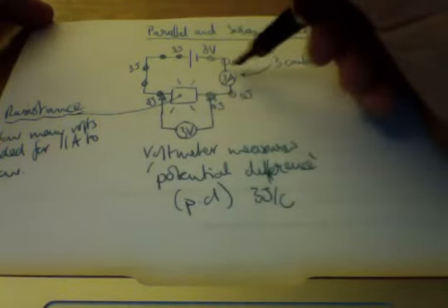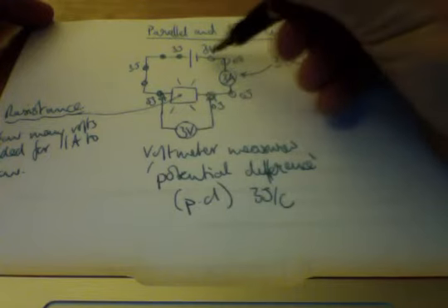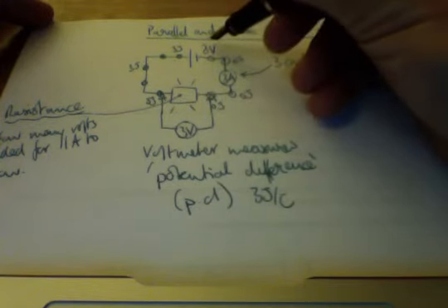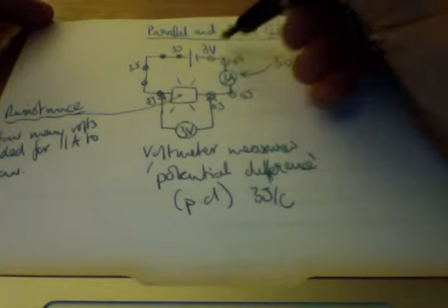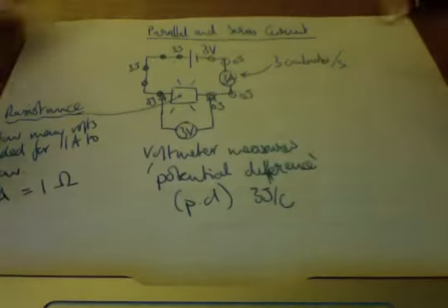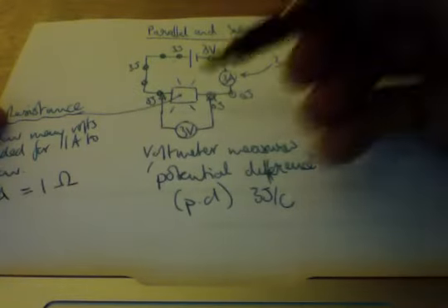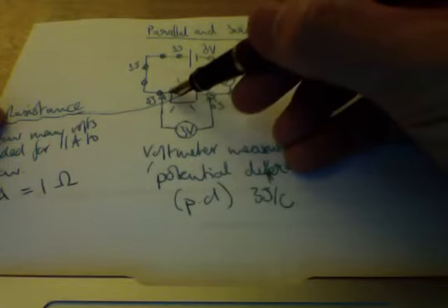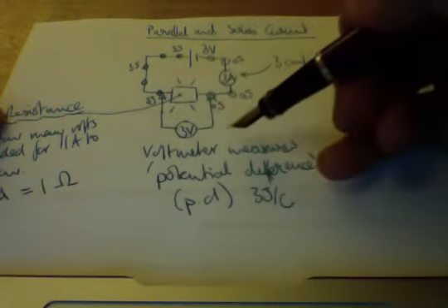In this case, I have 3 amps, and 3 volts are delivering that. So therefore, in order for 1 amp to flow, I must have 1 volt doing so. So in this case, I'd have 1 volt per amp, which is the same as saying 1 ohm. So just remember, resistance says how many volts do I need if I just want to create a 1 amp flow across it.